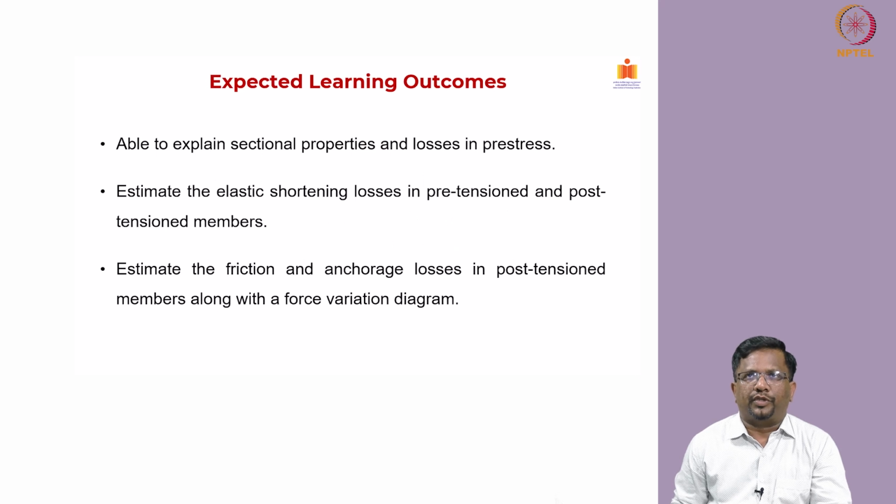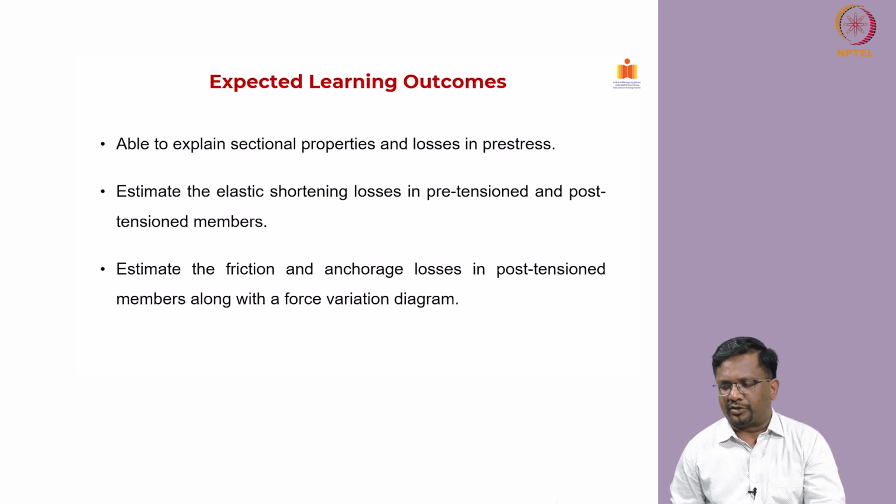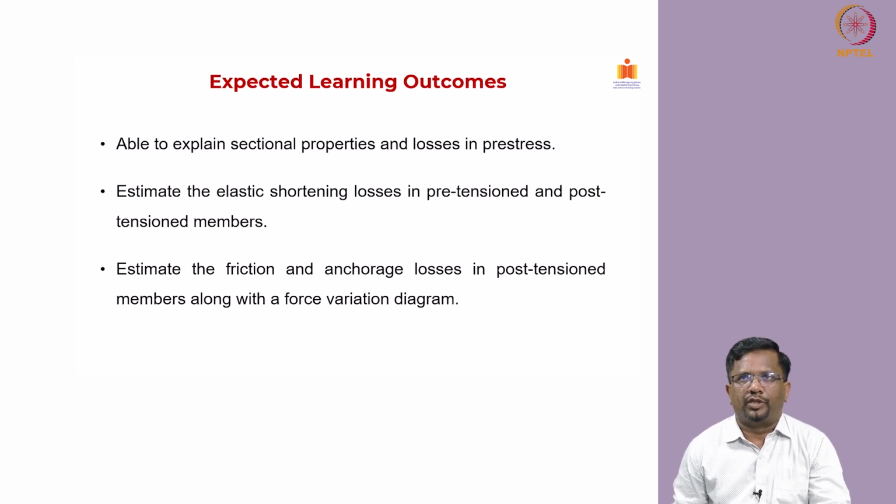After going through this video, the student should be able to explain the various sectional properties that will be used in the calculations of the losses in prestress, and estimate the elastic shortening loss in both pre-tension as well as post-tension members, and estimate the friction and anchorage losses in post-tension members, and also should be able to establish the force variation diagram.